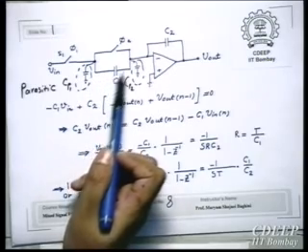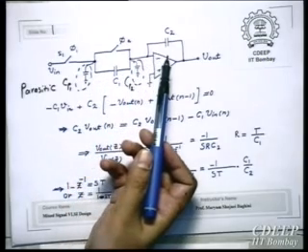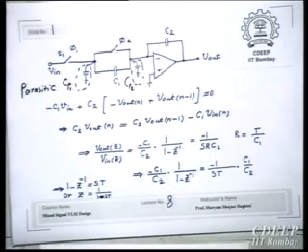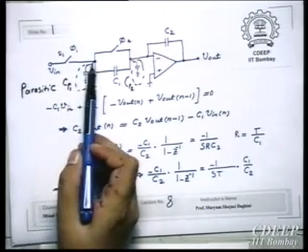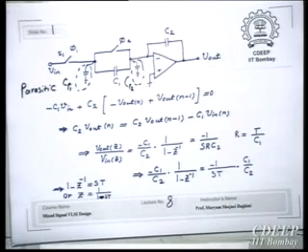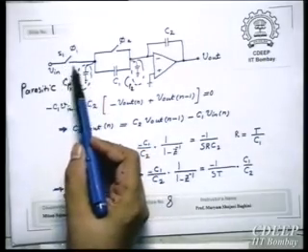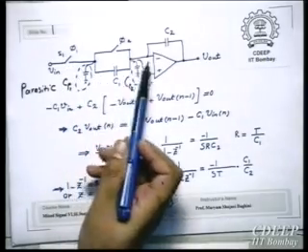And these two capacitors will charge to the new values. If you give it enough time, then after some time this current will be almost zero. Therefore, you won't have any drop here, and this node will reach Vin. And the additional charge is in fact coming from this Vin. Therefore, it doesn't have any impact on this.